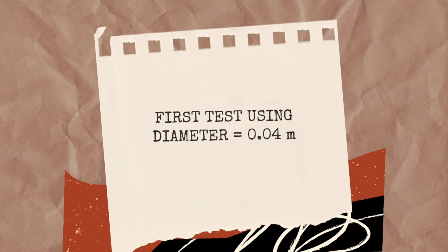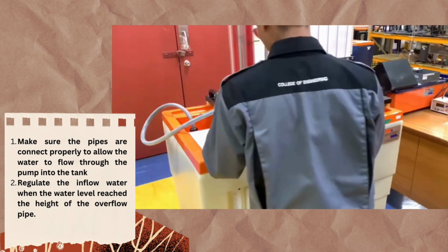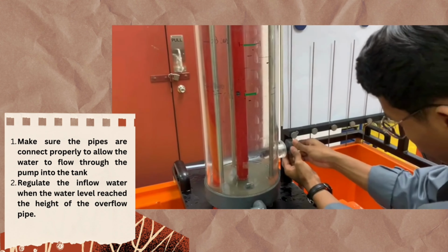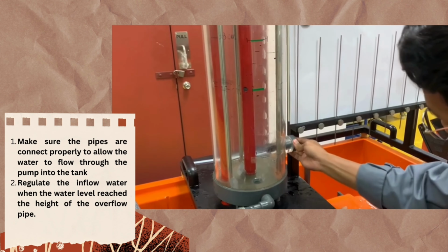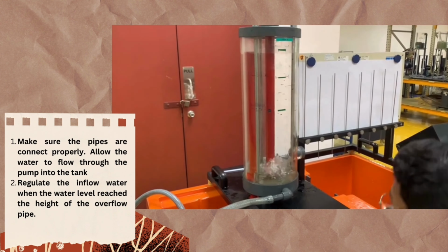Next, let's talk about the procedure. For our first test, we are using 0.04 meter of diameter. First, make sure the pipes are connected properly to allow the water to flow through the pump into the tank. Next, regulate the inflow of water when the water level reaches the height of the overflow pipe.